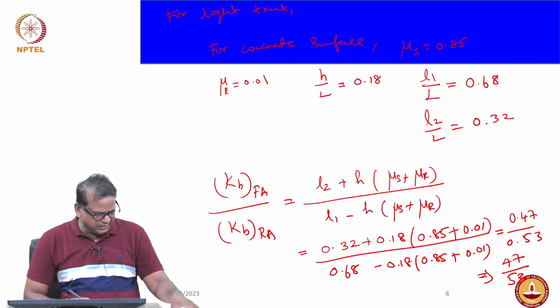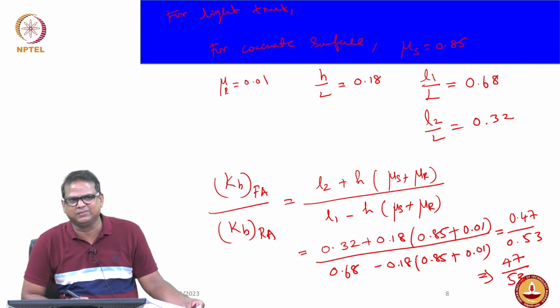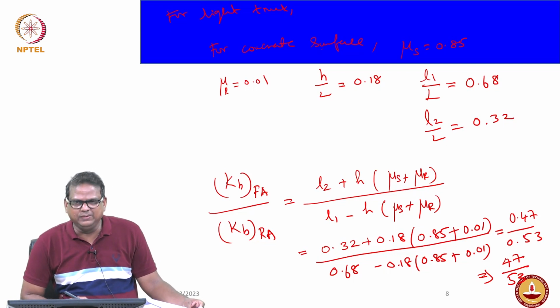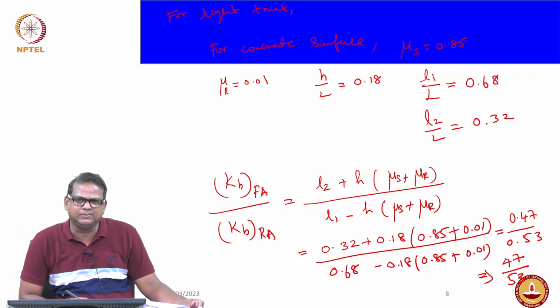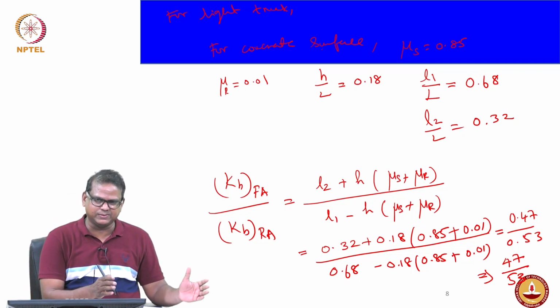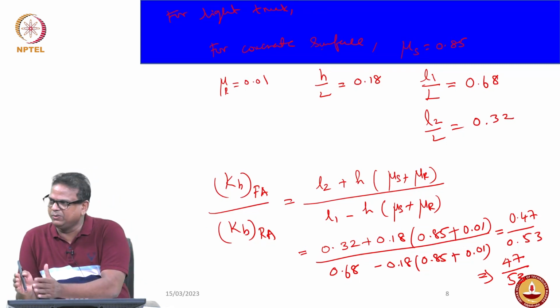Okay, what they asked: in a vehicle, at the front we have a disc brake, at the rear we have a drum brake. So how is the proportion going to work? That's the question that was raised. See, as I said earlier, the proportions are already taken care of by your wheel cylinder and hydraulic pressure, right. So whatever x proportion will go to the front axle, the remaining portion, say a y proportion, will go to the rear axle. Okay, so that is about the proportion only.